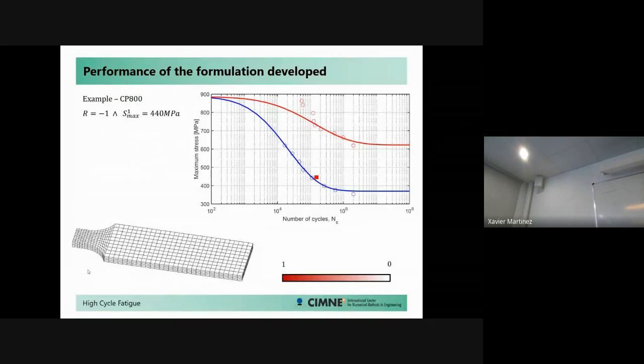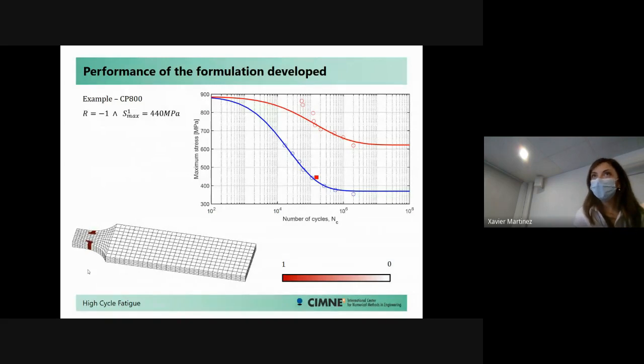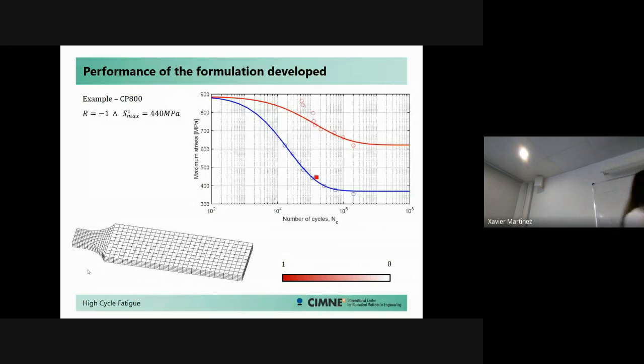For instance, this small discrepancy is due to this factor. When I reach this level of cycles corresponding to this blue dot over there, or to the blue line, let's say, this is when I will begin to have, in my numerical simulation, damage accumulation. Okay, I start to have nonlinear dissipation, damage starts to accumulate. And until it propagates completely, I spend the number of cycles between these 2 points, okay?